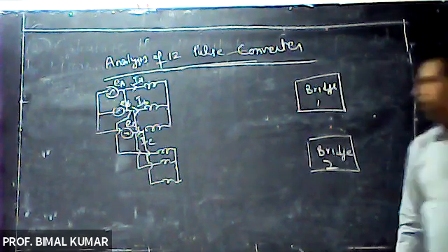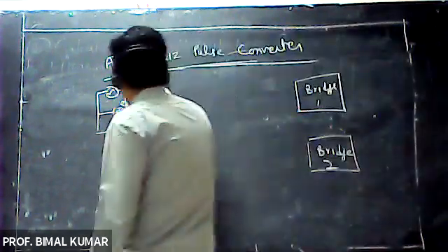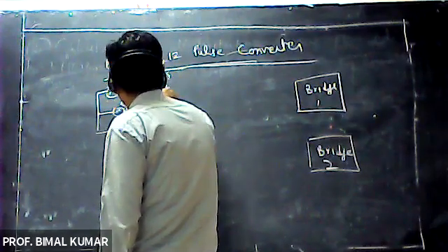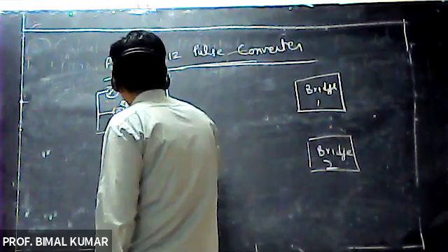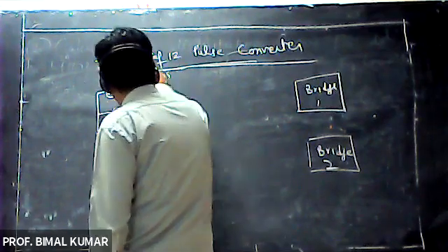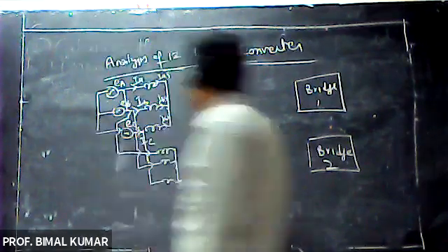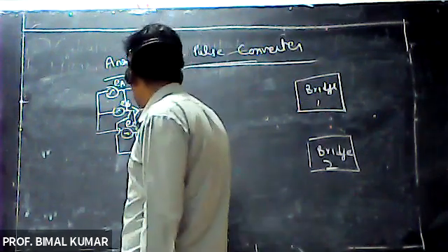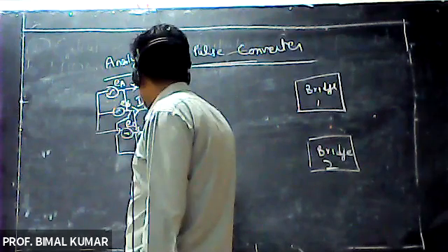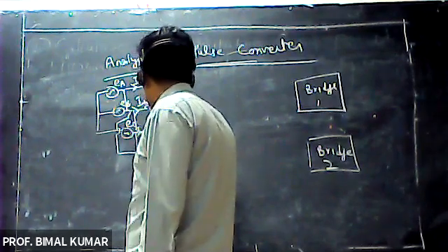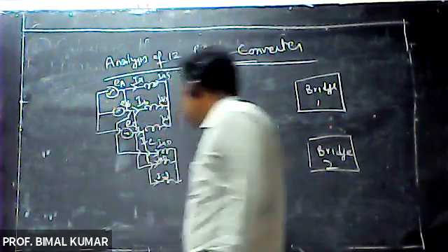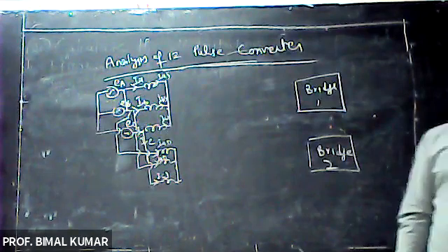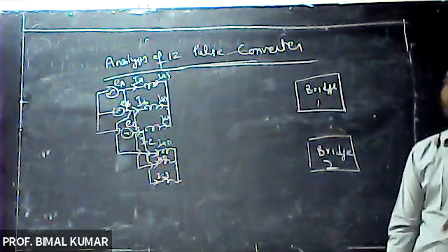Now, here I am denoting these with IAS, IBS, and ICS, because transformer 1 is of the star type connection. Now for the second, I am using the notation IAD, IBD, and ICD. Right? IAD, IBD, and ICD are the currents in the primary of transformer 2.